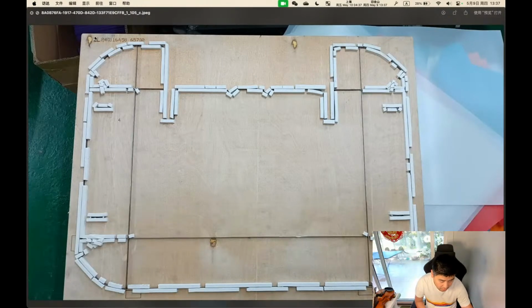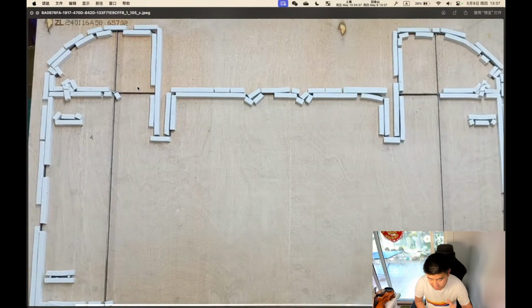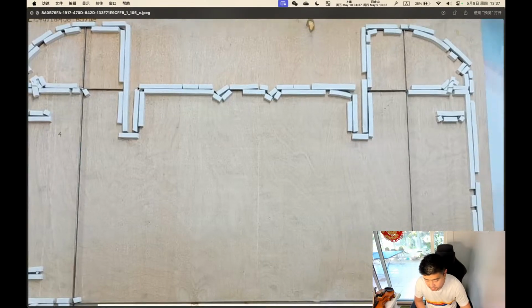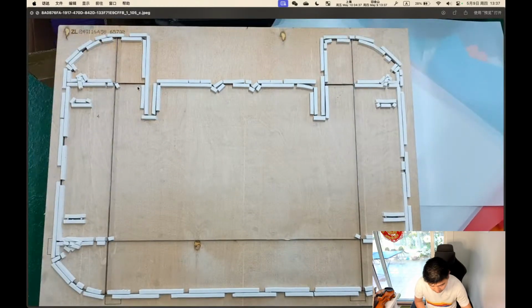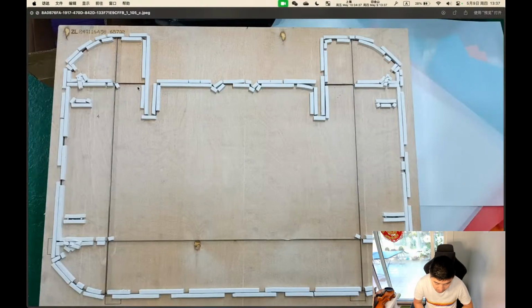It's very ingenious. You have a piece of plywood and you cut channels into it, and then you embed a metal blade, following that channel, right? And then you bend them, etc. And then this will become your cutting tool, right? So they slide it into a giant press, right? Ka-ching, you punch out the geometry in one go, right? So in mass production, that's just faster, right?